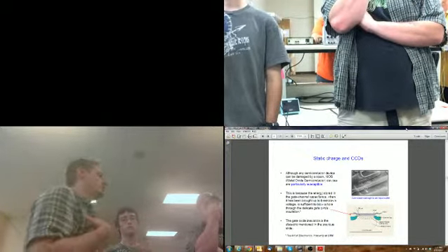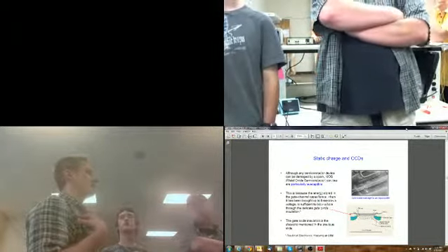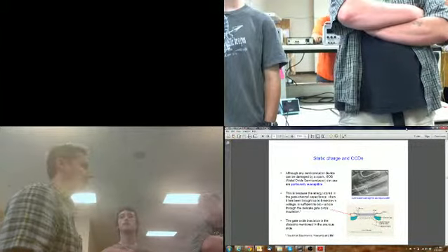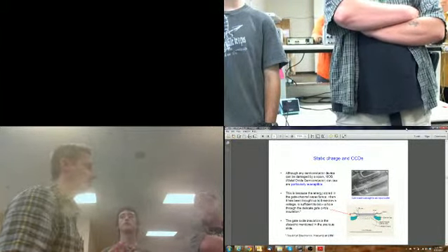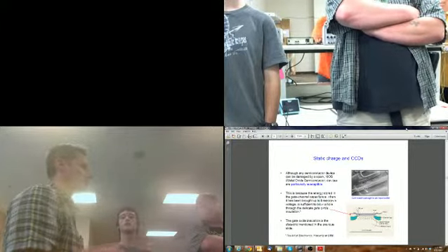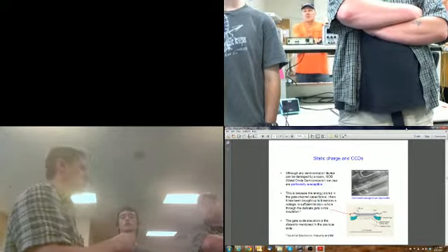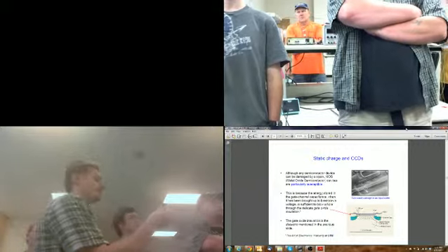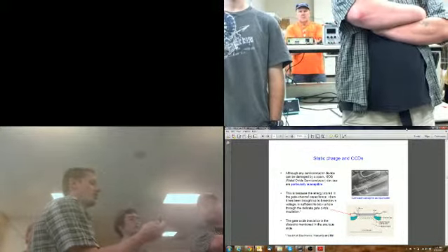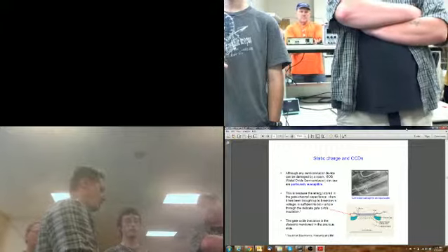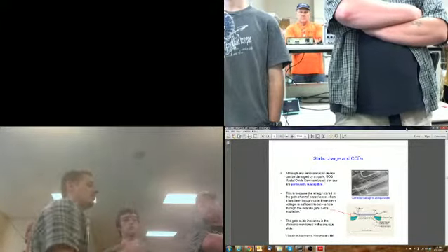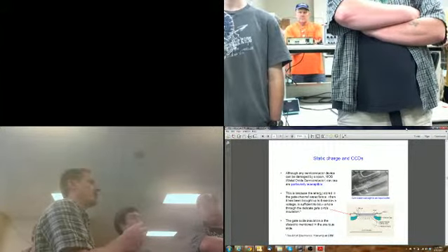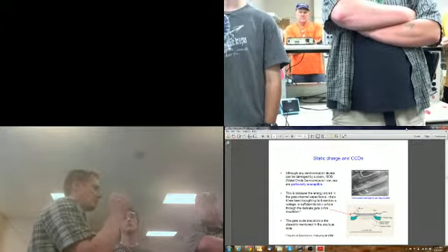So they have different models. Basically, the way they view your body is as a capacitor. A capacitor charged to 2,000 volts through a 1K resistor. That's the model that you are as a human. You're like a capacitor that's charged to 2,000 volts with 1K series resistance. That's how you're viewed from an ESD standpoint. And so when you touch this, it's going to charge through you to the part. So the little modules they put in there protect against the spike? Yeah. So these chips have probably all been weakened by ESD, but the only reason they still survive in your phone and everything is because precautions have been made. Now, that doesn't mean it's only 2,000 volts. And that's only assuming one shock.